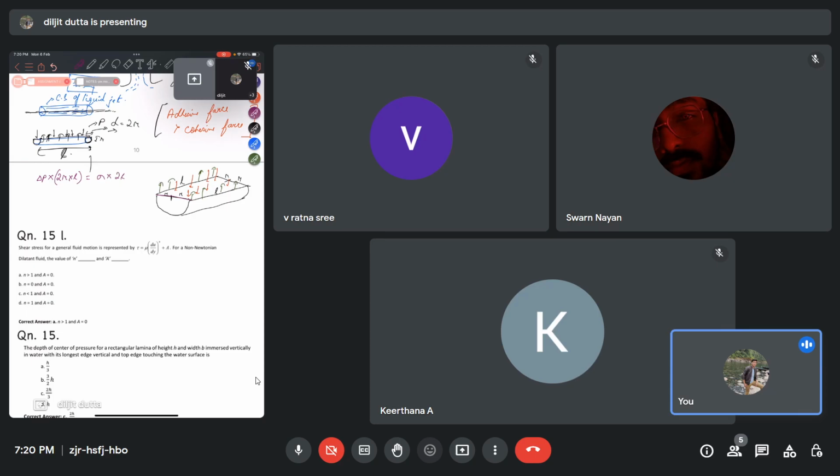Sigma, because we are working only on these sides, so L plus L, 2L. So this is where surface tension is acting. So this is the balance. You can cancel 2 by 2L by 2. So delta P equals sigma by R.